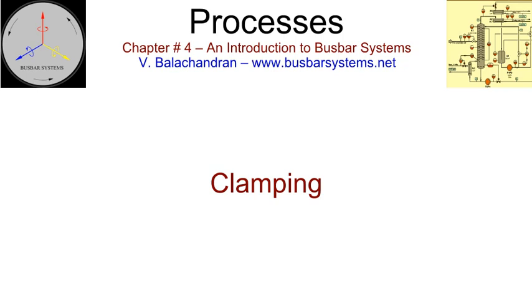When the clamp is of a different material from that of the conductor, it is susceptible to the formation of a galvanic cell. Clamping is also universally adopted in the sandwich bus and low-voltage cast resin bus, for jointing the conductors of the adjacent sections.